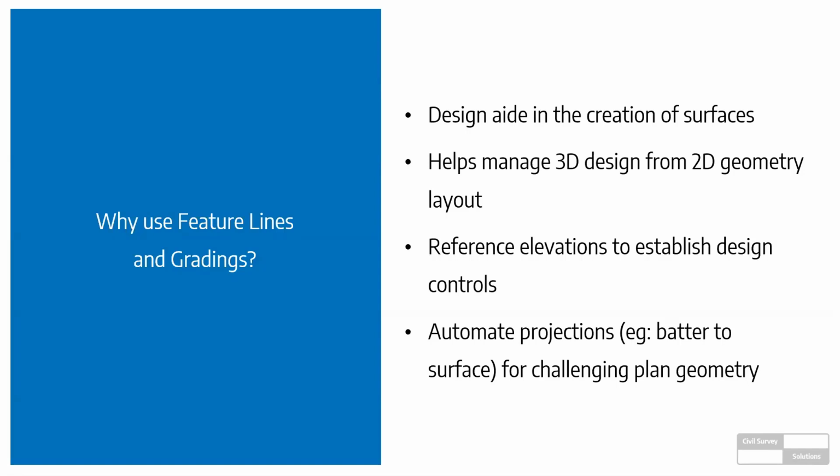So in and of itself, you use the feature line to build up a terrain. You basically build grade breaks for features like building pads, bottom of retaining walls, top of retaining walls, detention basins, a split somewhere for elevation change. And it really is a great tool for you to work in 2D, but have a separate interface to talk about and describe the 3D design elements.